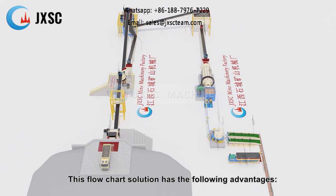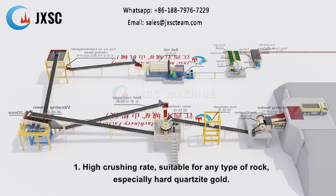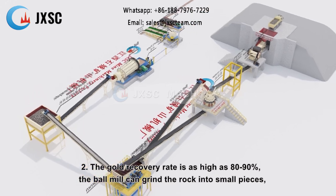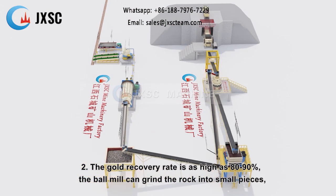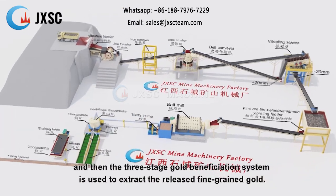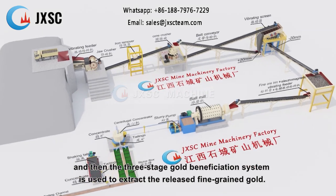This flowchart solution has the following advantages. 1. High crushing rate, suitable for any type of rock, especially hard quartzite gold. 2. The gold recovery rate is as high as 80 to 90%. The ball mill can grind the rock into small pieces, thereby releasing more fine-grained gold from the rock, and then the 3-stage gold beneficiation system is used to extract the released fine-grained gold.